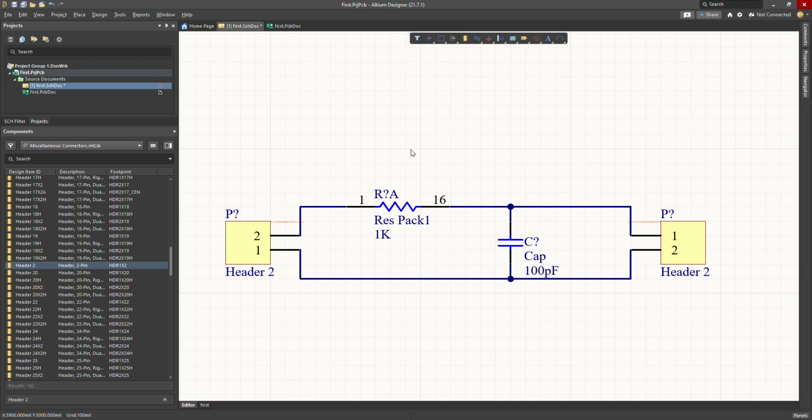For a schematic to work and for Altium to be able to understand and generate the parts correctly, and for the manufacturer to be able to pick and place the parts in the correct spots, every single component has to have its own unique identifier or unique reference designator.